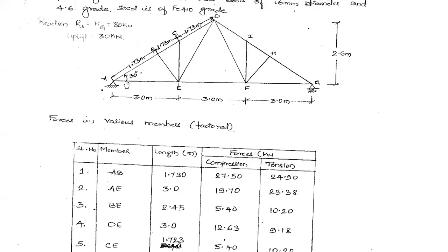Okay, in case you don't have this angle mentioned in your question or not available to you in the diagram, in that case I can consider this height and half the span of the truss and go for finding this pitch angle. Like that you can obtain the pitch angle. Okay, and whatever lengths are not available, which will not be given to us.